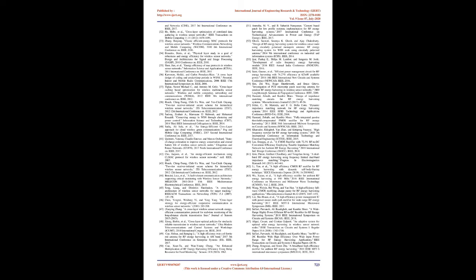Dolia et al. 2018 proposed a small antenna for RF energy harvesting, claimed to improve the efficiency by using the voltage doubling concept. The receiver antenna is a multi-band monopole design implemented for the purpose of increased gain and unidirectional radiation pattern. At each frequency band special types of voltage multipliers are implemented to increase the output power. The design of antenna and rectifier is carried on a single FR4 substrate to increase PCE to 85%.